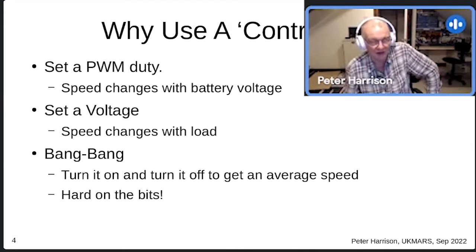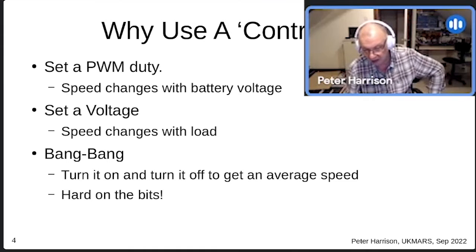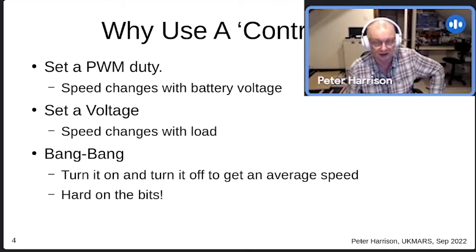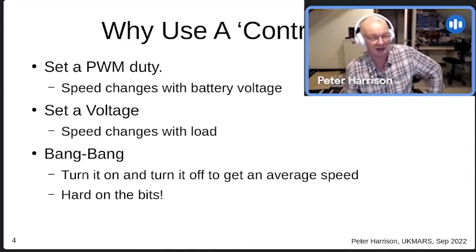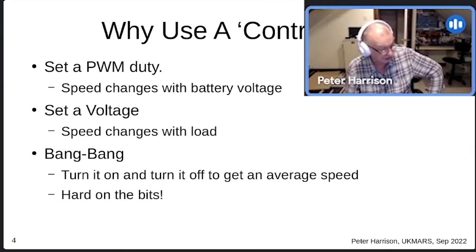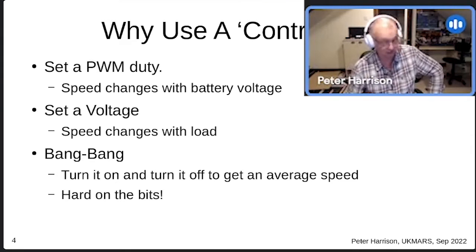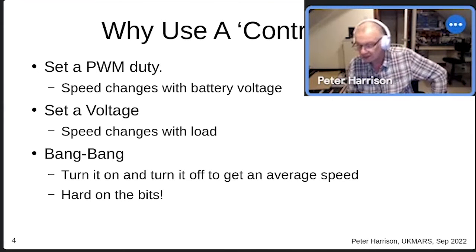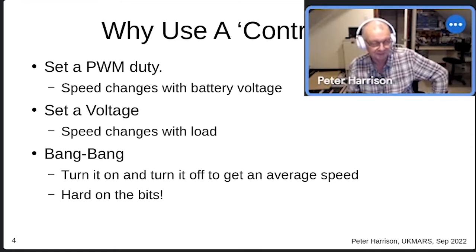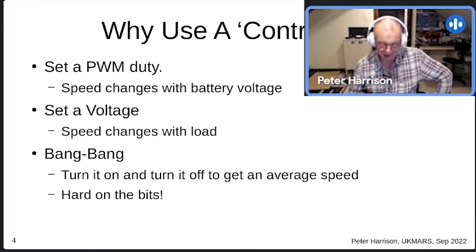If you want to drive the whole thing at a constant speed, you might, and I've seen it done, just say, it's going too fast, I'll stop driving it. It's going too slow, I'll start driving it. In fact, I used to work with somebody who operated their car that way. It was most disturbing. That's called bang-bang control, and it works, not terribly well, and it'll wreak havoc. Your gearbox will be slammed in forward and then slammed on the brakes and then slammed forward again and so on. But it'll work. It turns out, though, that we can do better.